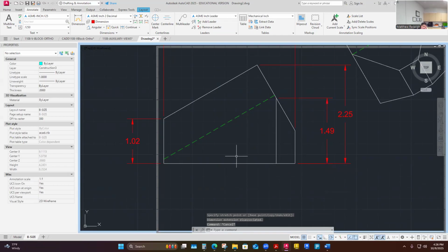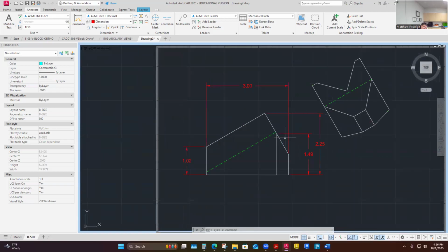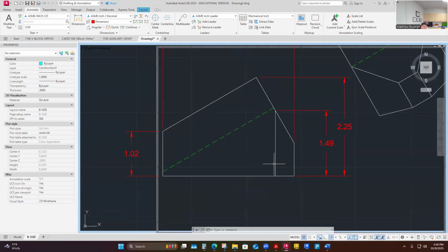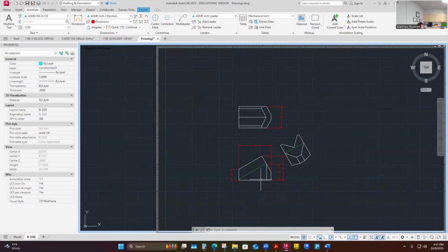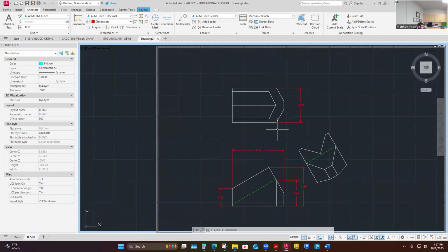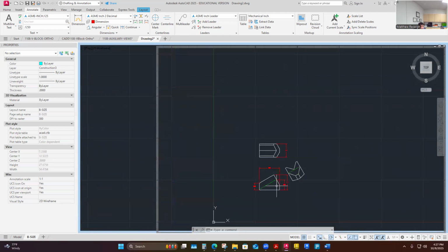Okay. So that's this height, and then I've got this height. But what I don't have is a point in the other direction. I feel like I've locked in the height of this, but I need to lock in where it is in the X direction for this point, or maybe this point, or both. So should I pull the dimension down here? Should I pull the dimension up here? Wherever I choose to pull is going to establish another control.